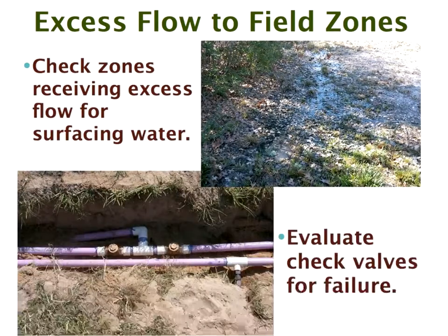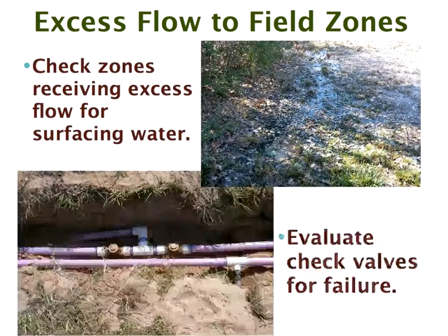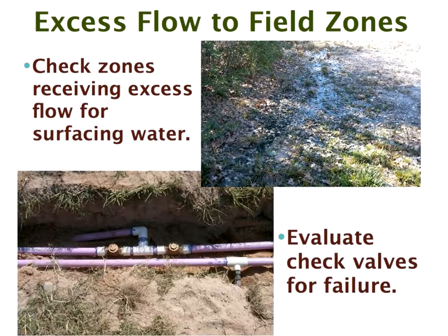Check the field, walk the field, and if you have something like a gopher strike, or we had one where the kids pitched a tent on the drain field. It was a beautiful piece of grass, because of course the grass was growing beautifully under the drip line, and the children went out and pitched a tent out there and drove their tent poles through the drip line. I mean, these things happen. You'll see it straight away. I mean, there you get just such a large amount of flow. You'll see straight away, you'll see the water, and just dig down and put in a coupling. Okay.